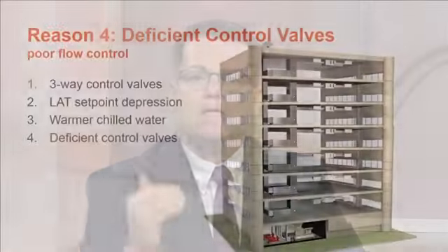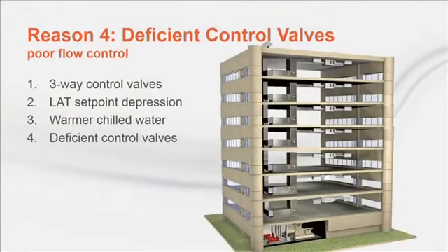To avoid valve-generated problems, it's imperative for the engineer to specify high-quality valves selected for the operating conditions of each specific air handler. This was driven home to me recently during work at a high-rise building in Atlanta. Each floor had identical air handlers and chilled water control valves. The chiller plant and system pumps were in the basement.